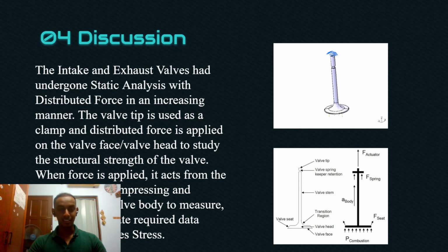So for the discussion, the intake and exhaust valves underwent static analysis with distributed force in an increasing manner. We decided to do a static analysis with distributed force on the intake and exhaust valves. We know that the valve is a constantly moving component. In an engine, the valve has to open and close all the time, during the intake stroke or the exhaust stroke. So we decided that the valve would be the simplest study for us to do an analysis on,